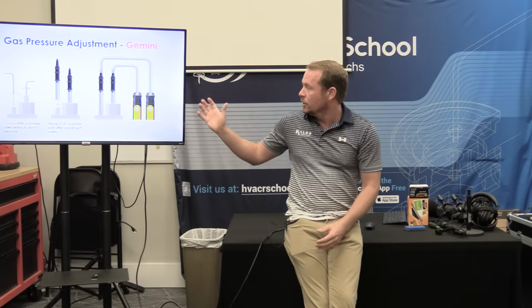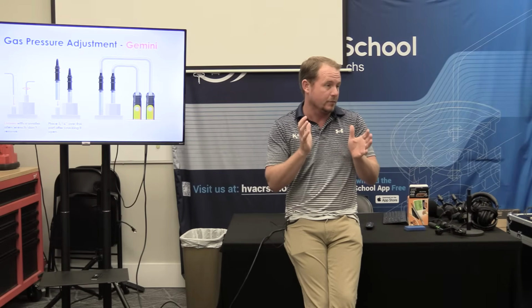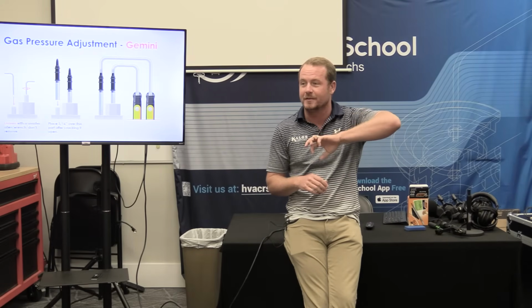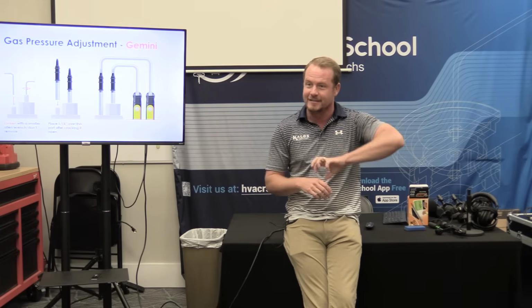In simple terms, there are only really two ways to make a pressure measurement. Either it's a differential pressure or it's a zeroed pressure, which is still a form of differential pressure. It's just making a pressure measurement relative to something that occurred in the past, a zeroing out. You zeroed it out and said, all right, here's my baseline, and now here's the pressure measurement. The reason that's important is that the pressure in the room doesn't stay the same.